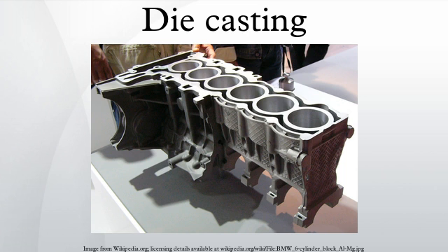Then a precise amount of molten metal is transported to the cold chamber machine where it is fed into an unheated shot chamber. This shot is then driven into the die by a hydraulic or mechanical piston. The biggest disadvantage of this system is the slower cycle time due to the need to transfer the molten metal from the furnace to the cold chamber machine.